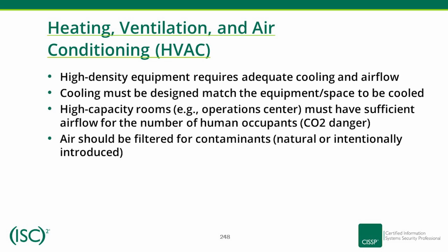Heating, ventilation, and air conditioning. HVAC: high-density equipment requires adequate cooling and airflow. Cooling must be designed to match the equipment/space to be cooled. High-capacity rooms, for example, an operations center, must have sufficient airflow for the number of human occupants. CO2 danger. Air should be filtered for contaminants, natural or intentionally introduced.